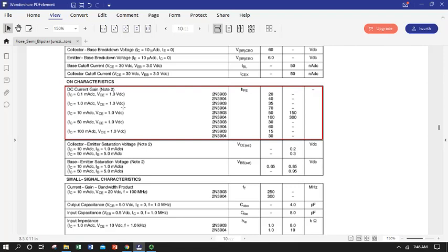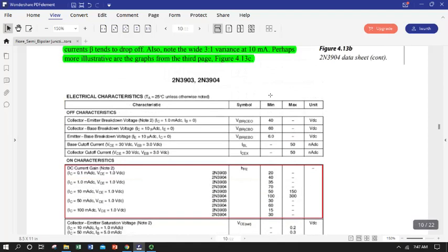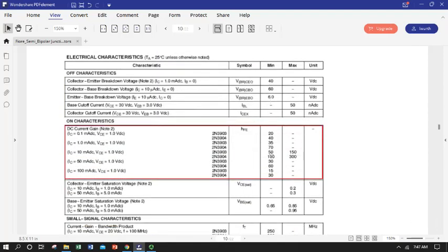So the spec sheet basically assumes you're applying 1 volt DC collector to emitter, and then it gives you either a minimum or a range of betas depending on how much current's flowing. And you can see that your betas for really, really low collector currents are 20. It's still respectable. It's an order of magnitude gain, but nothing fabulous. And likewise, if you're asking the device to give you a lot of current, your betas are modest. But in the middle, you get some pretty screaming high betas.